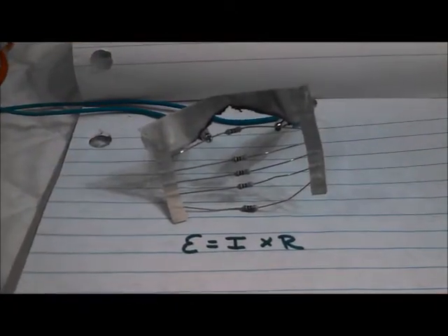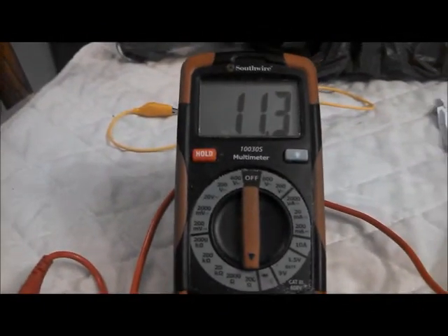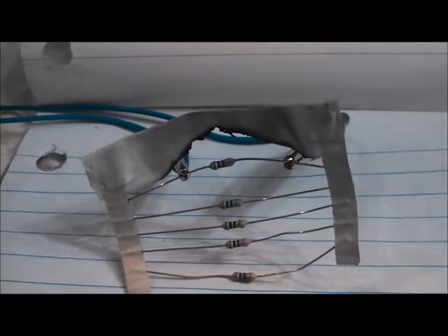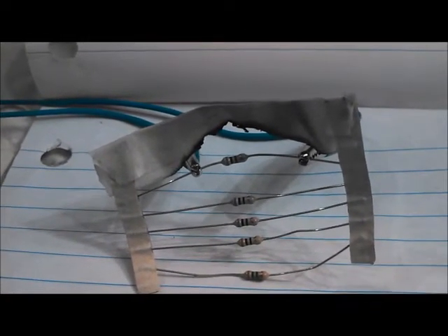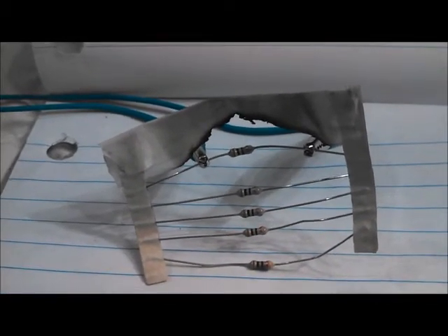These are the resistors we burned up in class. Clearly you can see the tape actually caught on fire. This is supposed to be a 10 ohm resistor. I don't know why it's reading 11, but it is reading the brown, black, black. That would be 10. The 5% should be half of an ohm difference, and why it's reading 11, I don't know. But let's look at what happens with the math.